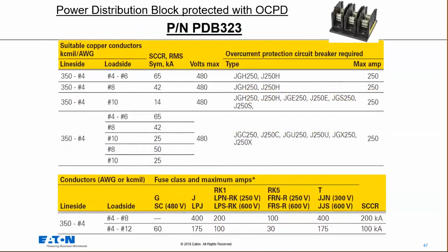If it's unmarked, I think that's what they were trying to say. I'm not too sure. Well, if it's only 1059, you have to see whether it's a recognized part or not. If it's a 1059, it's not going to be good in a feeder circuit, and you could probably use it in the branch circuit as long as you keep the minimum space requirements. And in those cases, if it's unmarked, you'll have to use the standard fault values that you'll find in the tables in supplement SB. I believe it's 10,000 amps in that case, but I'll have to verify that.